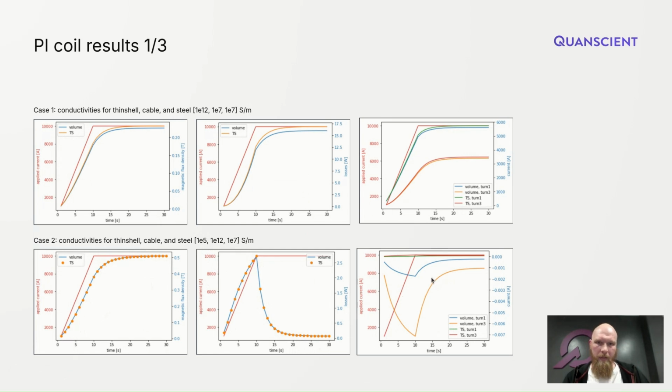However, you can see differences now in the net currents. However, if you compare the amplitude of the current, it's negligible compared to the applied current. So this is basically a noise level signal in the Thinshell, and this can be really affected by the mesh as well. So the mesh is not that accurate in the Thinshell model anymore, since we are using bigger elements there.